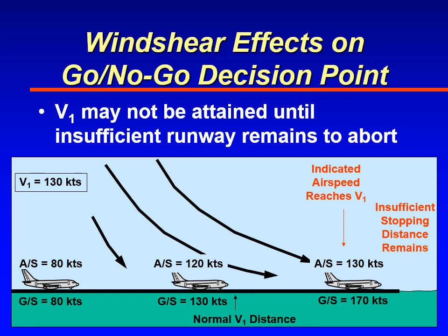Of course, if you're on the runway, the airplane doesn't accelerate very rapidly. So you are probably below your rotation speed, and for that matter, perhaps your decision speed. If you're below your decision speed and there's runway remaining, you can stop on the runway. But if you're still below the decision speed or even rotation speed, and there's not much runway left, then you know you're going off the end of the runway and you need to get the airplane airborne.